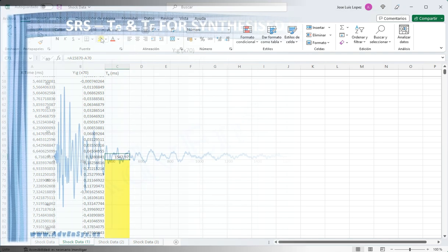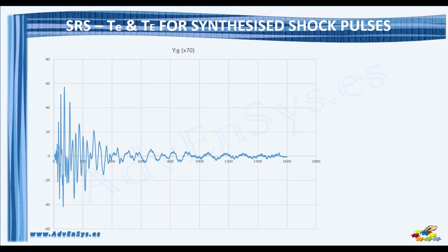15,800 rows. The highest concentration of energy interval, T capital E, is defined as the minimum length of time that contains any time history acceleration magnitudes exceeding in absolute value acceleration peak divided by CF, being acceleration peak the highest shock peak amplitude, and CF is the crest factor, defined as the ratio between peak acceleration and the corresponding RMS values associated with the single shock.